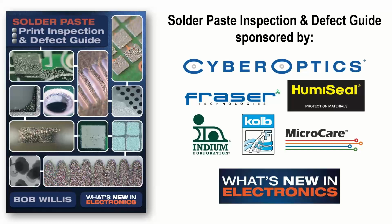What is the best ideal solder volume for BTC thermal pads? It's a good question. It's not really the volume, it's the position of the paste. With BTC or LGA, QFN packages, if you get the paste positioning wrong or just get too much, you get too much volatile material underneath the package. The package then floats during reflow, and you sometimes get some open circuit joints because of that floating action. You will certainly get a lot more voids. So less is more on BTCs.